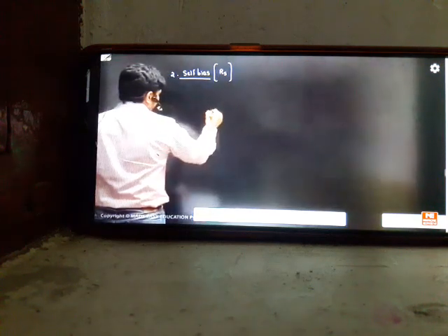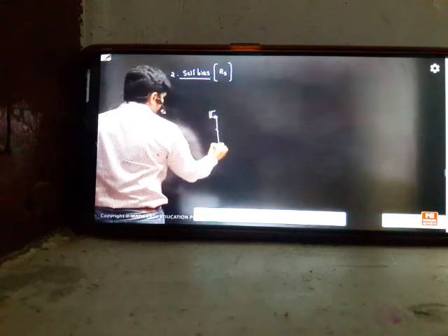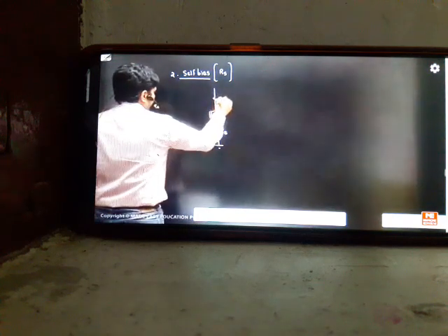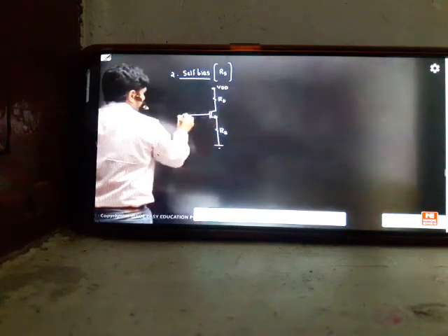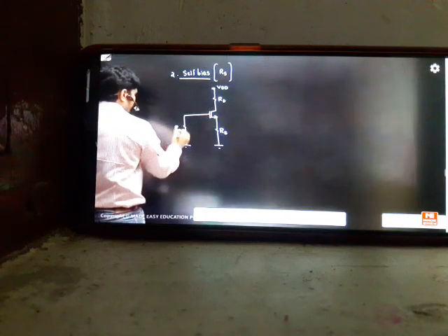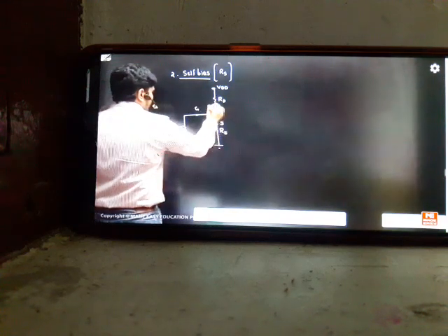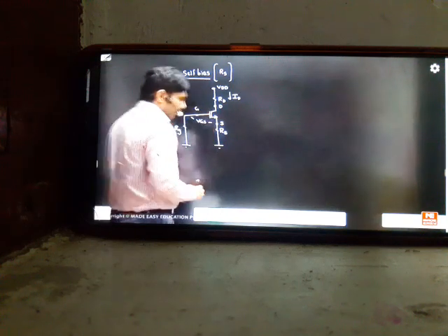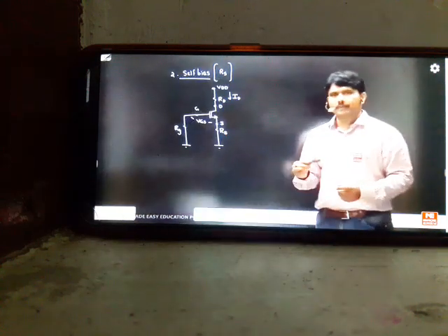So what is the change in the design from the previous topic to the present one? In fixed bias we don't have RS, in self bias we have RS. And RD is common, both have RD. This is VDD, and we have here one RG to ground. This is RG. This is gate, this is source, this is drain. This current is ID, and this voltage is VGS. So can you understand how to recognize the difference between a self bias and a fixed bias?